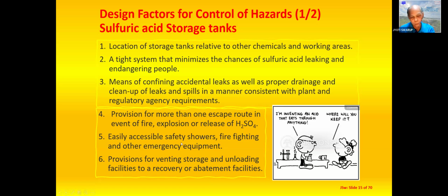Provision for more than one escape route in the event of fire, explosion or release of H2SO4. Easily accessible safety showers, firefighting and other emergency equipment, and provision for venting, storage and unloading facilities to a recovery or abatement facilities.